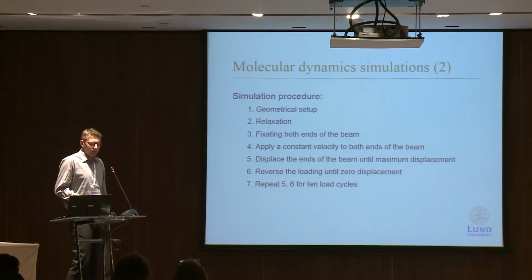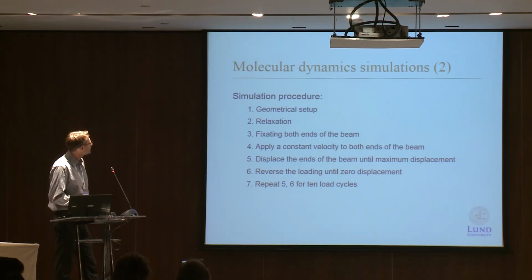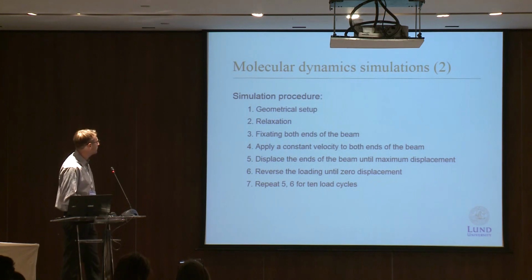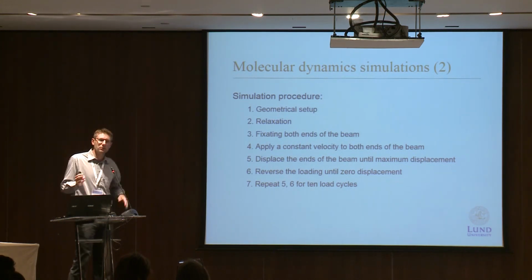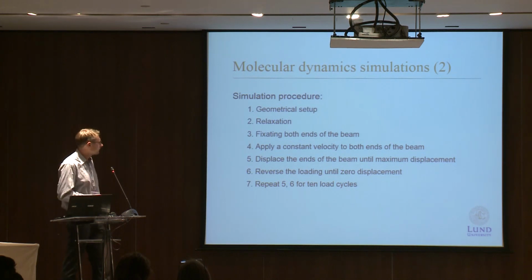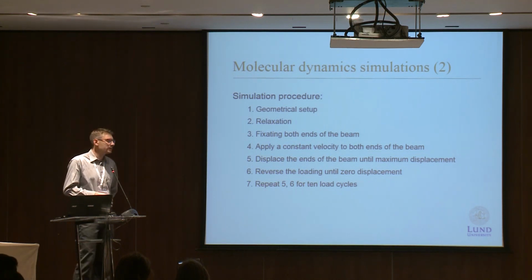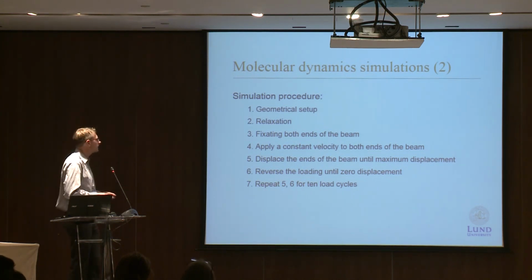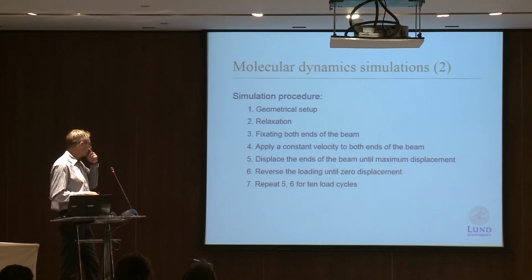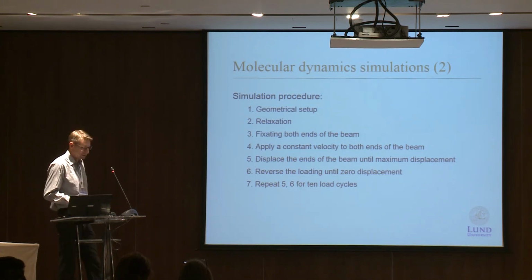We use a standard setup for the molecular dynamics simulations, nothing strange. We do a geometrical setup, then a relaxation to find the correct starting positions. Then we fix both ends of the beam, so it's like clamped ends. Then we apply a constant velocity to both ends of the beam, one in the positive direction and one in the negative, so we have a symmetric loading situation. Then we displace the ends of the beam until we reach the maximum displacement. Then, of course, we change the direction of the velocity and reverse the loading until we reach zero displacement. We do this for up to 10 load cycles unless the beam breaks before that.